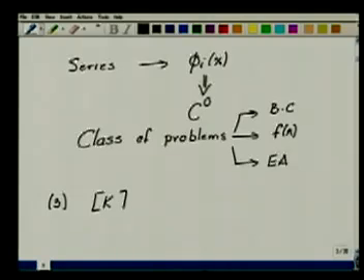That is, the stiffness matrix was sparse. Not only sparse, it was banded. That is, some of the elements around the diagonal, that is on either side of the diagonal, were only non-zero. Everything else in the matrix was zero.